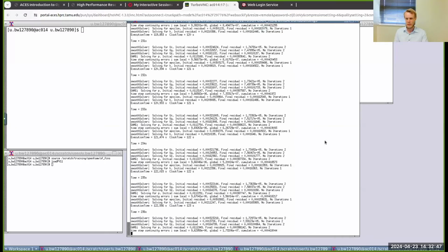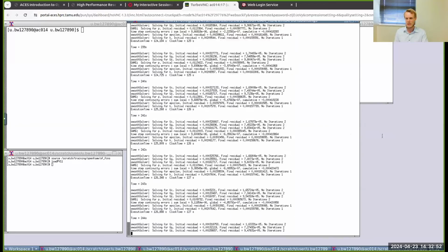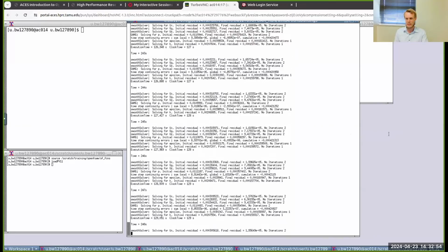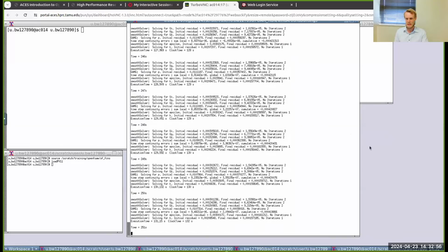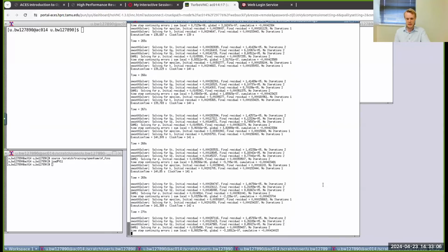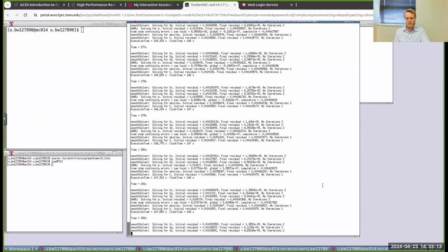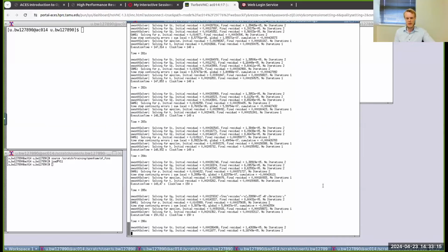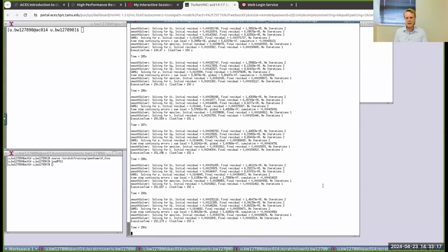I saw that if your snappyHexMesh creates a folder 1 and 2, that means you didn't put the overwrite flag on it. So it writes a separate instance for each step in the snapping process. And that's not very useful. Well, you can have it that way, but then you have to remember to start from the latest time, which this does by default.